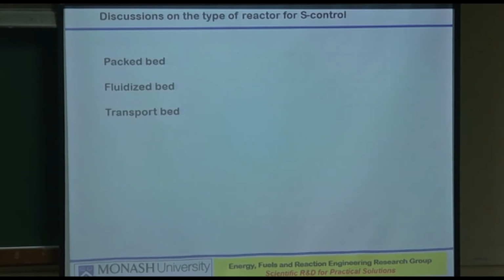So that is also correct, but it is also correct that if it is too fine a particle, which is necessary for good capture, it can give too much of a pressure drop, which can be counterproductive. Then the way to prevent the particles from agglomerating with one another is actually to keep them fluidized in either the fast fluidized regime or in the transport regime. And if you have the transport regime, because you are using too fine a particle, you need to bring them back through a small recirculation leg of its own.